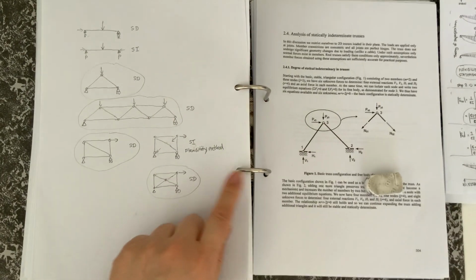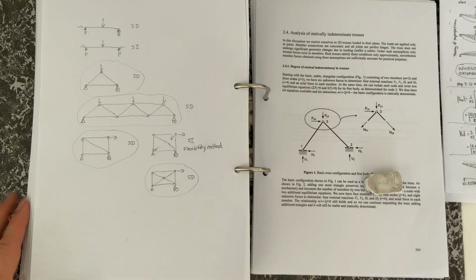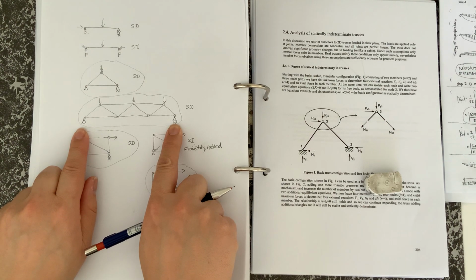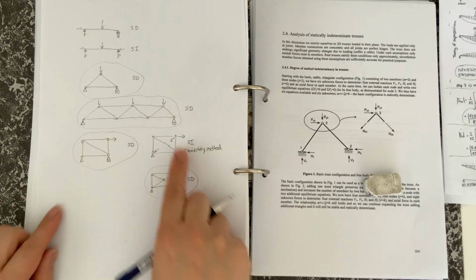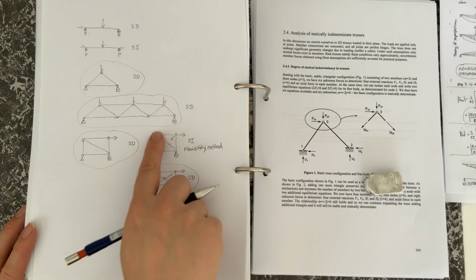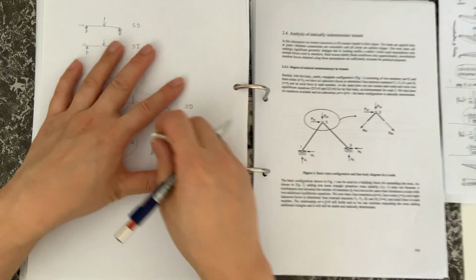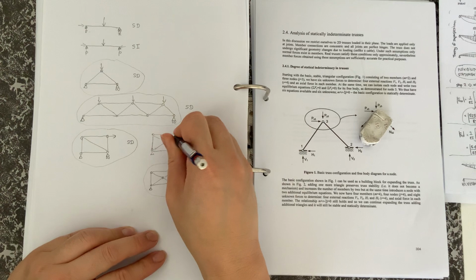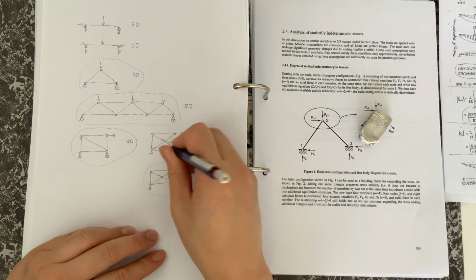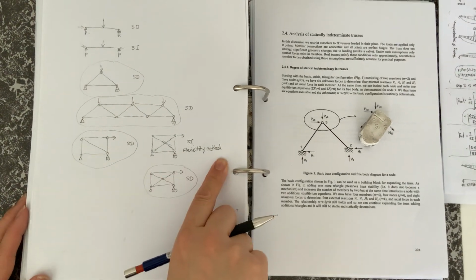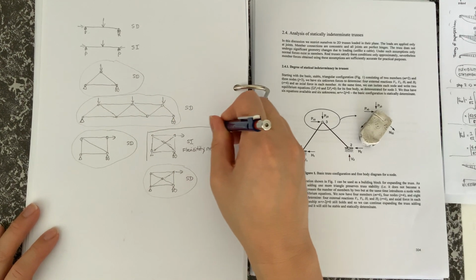But that's jumping ahead. So here I just want to establish that a structure can be statically indeterminate because of its supports. If I put that as a roller, then again, if I put that as a pin, then again it's statically indeterminate. But if the supports make it statically determinate, then this one here would become statically indeterminate because of the extra member that has been put across as a result of the two diagonal members crossing each other, okay? And for this type of structure, we would be using the flexibility method.